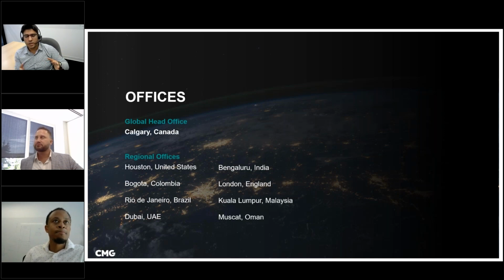For instance, say we have 100 grid blocks in the I direction, so we know that an injector well can move from 1 to 100 in the I direction, and the same for the J direction and K direction. CMOST will automatically generate multiple IJK values, which ultimately define the location of the well, and through this it will automatically switch and move the location of the injector wells, and it will find the best answer.